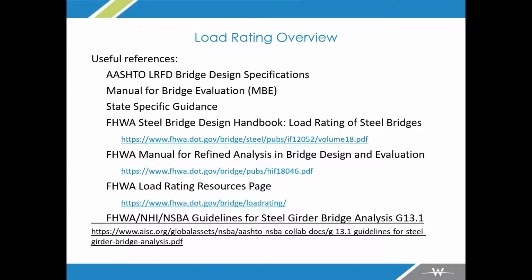There's a Load Rating of Steel Bridges handbook. I believe that is a little out of date now, but all the concepts are pretty much the same. So what you're really trying to do has not changed. Maybe a couple factors here or there, but if you see archived on it, don't worry too much about that. Yeah, you need to look at the current code, but in general, the concepts are not different. There's also an FHWA manual for refined analysis and bridge design and evaluation.